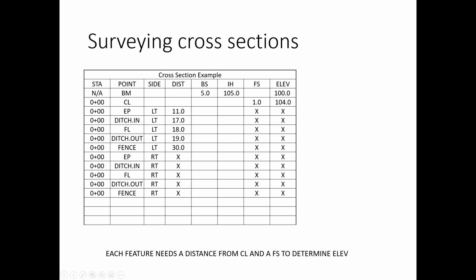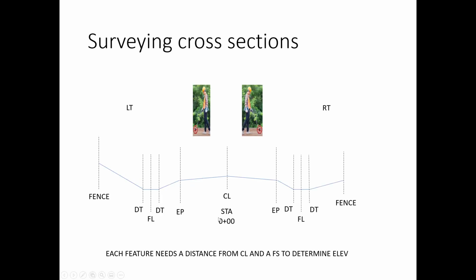And so we'll go back, and so now we're at station 1. We shoot the center line, each one of these features, measure them out, and keep moving down. It's a little bit tedious, but it gets kind of difficult doing it by yourself, holding the wheel, holding the data sheet, holding the rod, and carrying them all down with you. But it's kind of what you have to do unless you can find a really helpful assistant.